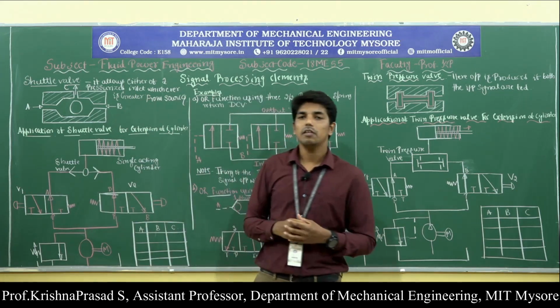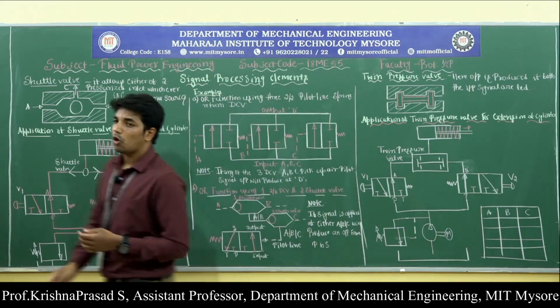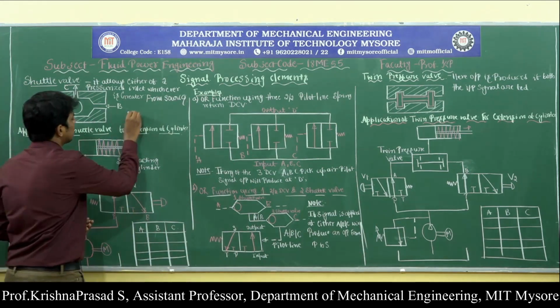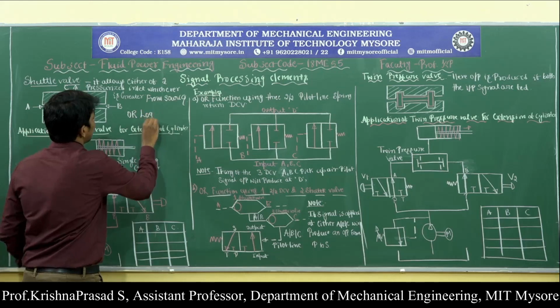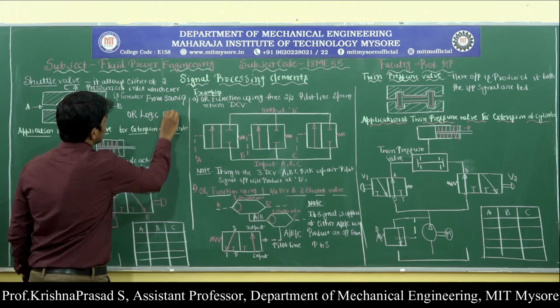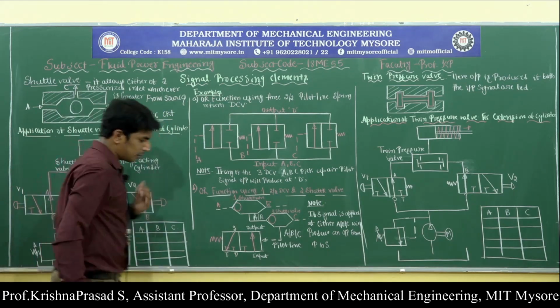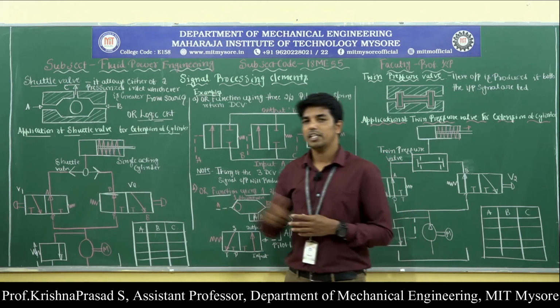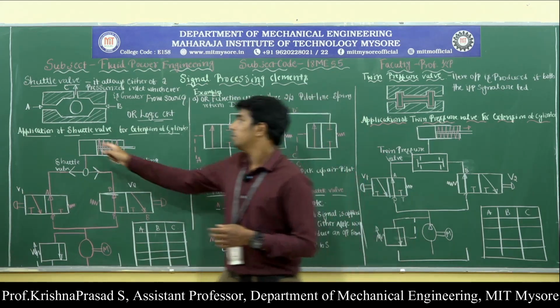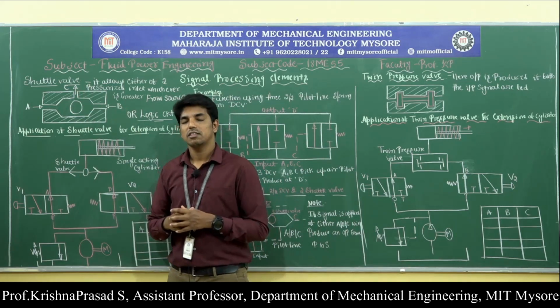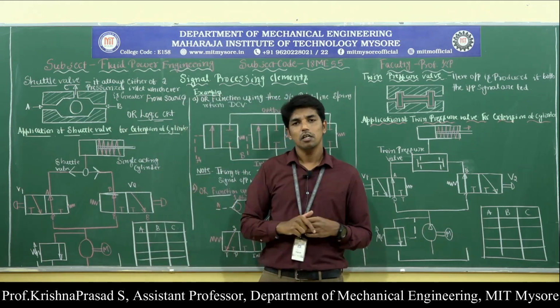Then, very important, the shuttle valve also acts like an OR logic circuit. That means if any one of the input signals is fed into the shuttle valve, then the output can be seen at the outlet port C. So, this is regarding the shuttle valve.